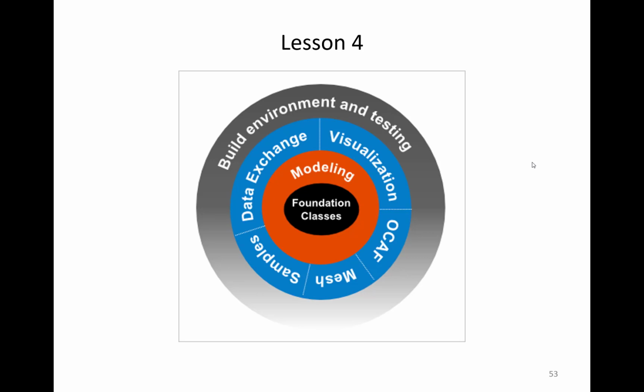If you remember, in the second lesson we learned how to bridge OpenCascade with VTK to visualize our 3D shapes as long as we model them. Today we are going to give a try to a visualization approach which is more native to OpenCascade, shall we say so. Instead of using VTK as we did in the second lesson, why not use what is called Application Interactive Services? One advantage of this approach is that we avoid additional dependencies such as VTK and instead leverage the full power of the OpenCascade library itself.